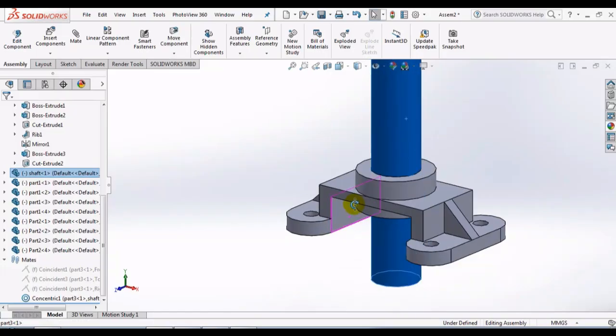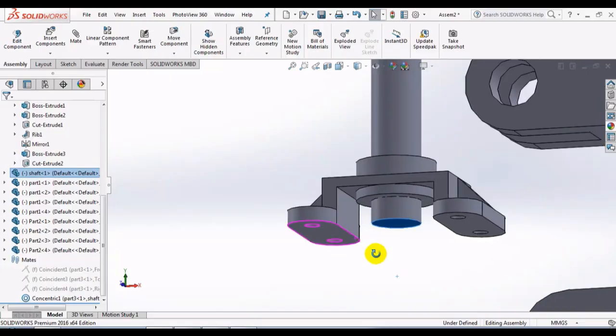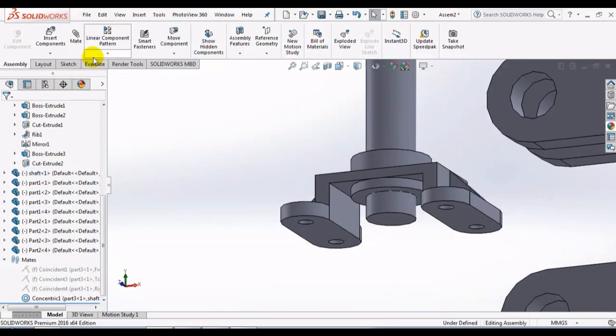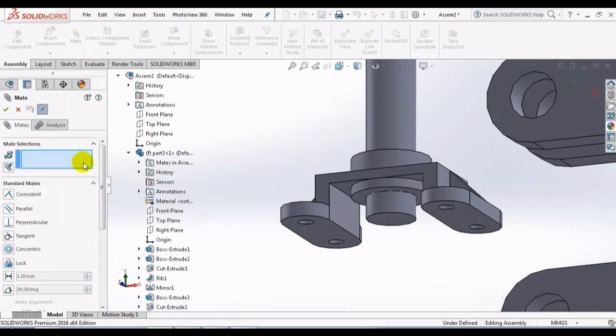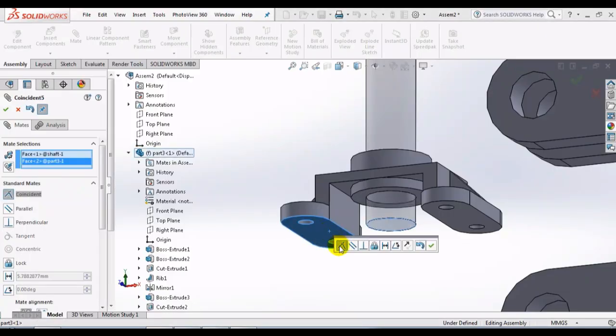So we can set the other mating, for the height position, to locate how to make it. So click Mate, and you can see the mating faces. We have to select the bottom face of the cylinder and the bottom face of the base. So you see that the coincidence is on, but we can make a coincidence like this at 0 position, same position, same plane.